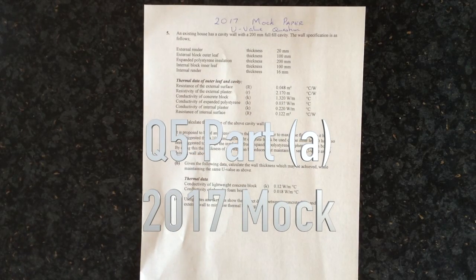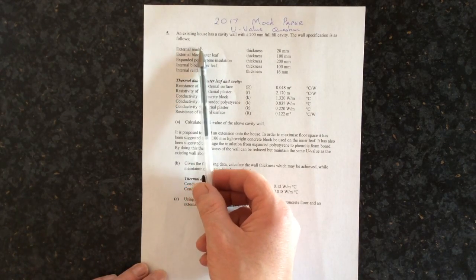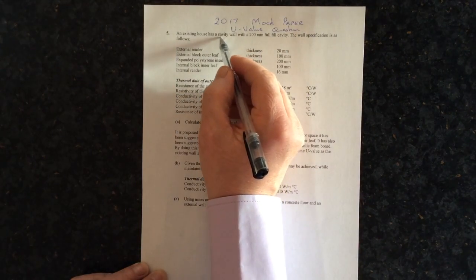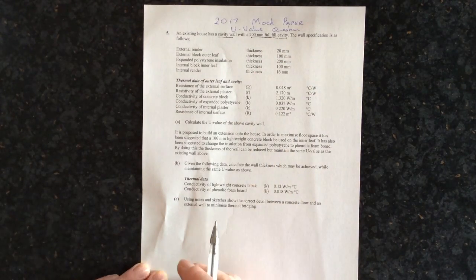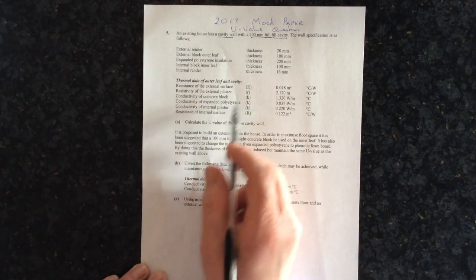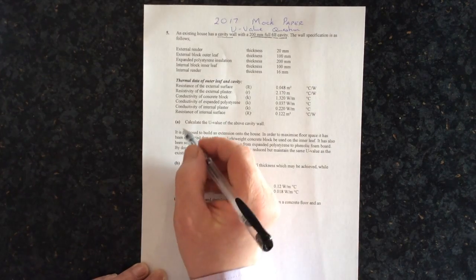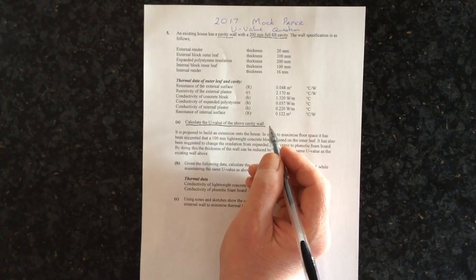Here, this is the mock paper from 2017, the U-values question. It's usually question 5 in the paper. So we're told that an existing house is a cavity wall with a 200mm full fill cavity, and that the wall has the following specifications. You're told the thickness of the different parts of it, and you're told thermal data of the outer leaf, inner leaf, and of the cavity. So the first part is you're asked to calculate the U value of the above wall.